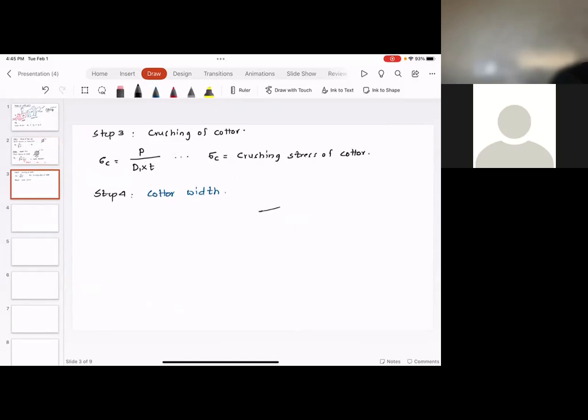Think about the quarter that is sitting inside the spigot, which could actually get sheared in double shear. So you could have the quarter get sheared something like this. This part goes one way, this part goes the other way. And now you have this resisting area. So this is in double shear.